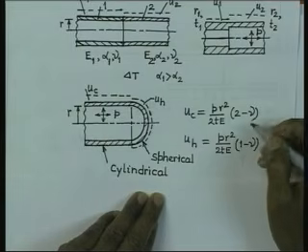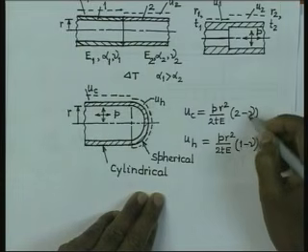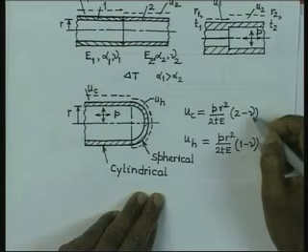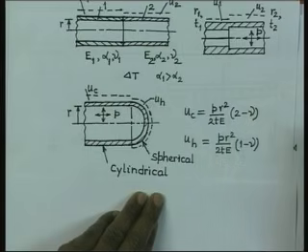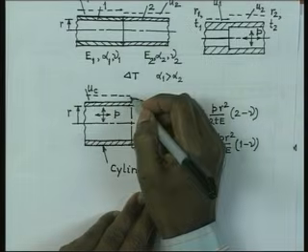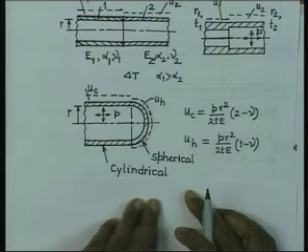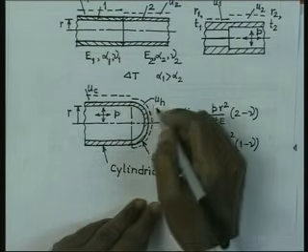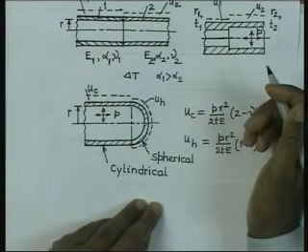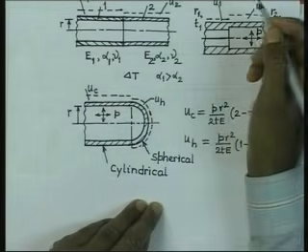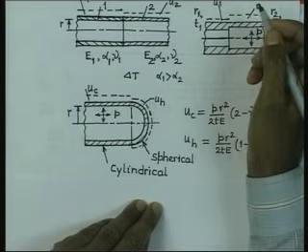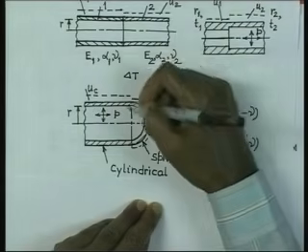Now, nu is generally very small, and if we forget about that part, the expansion of the cylindrical portion is going to be almost double. So, the expansion of the cylindrical portion is very large compared to the head expansion, and therefore, this portion is going to have a mismatch under the internal loading, and that will give rise to some local stresses.